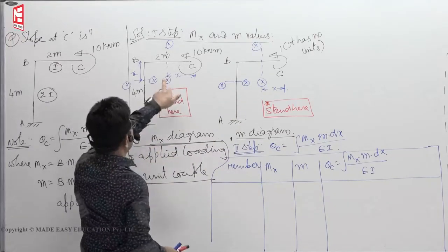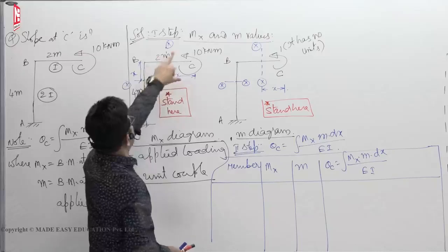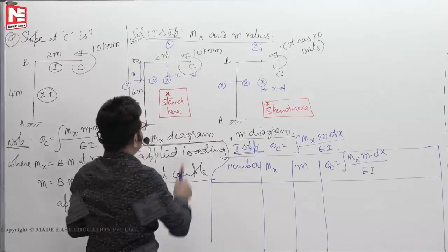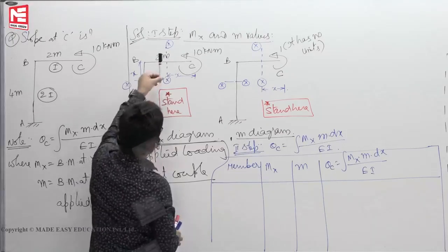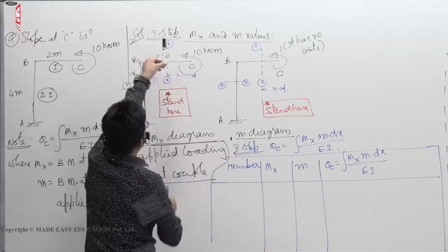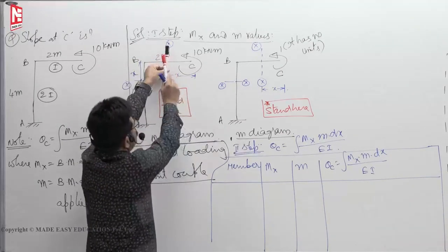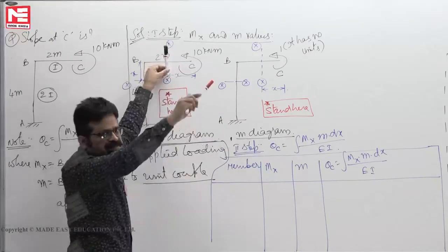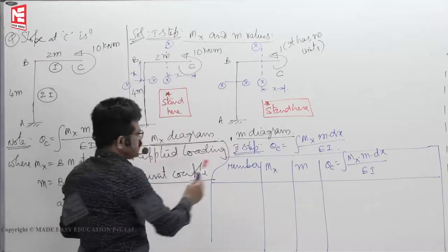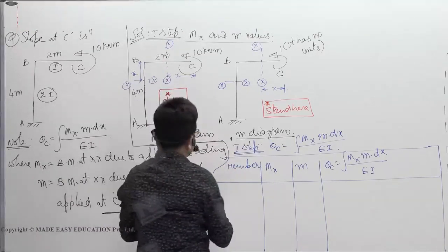Okay. Stand here means stand here, look right side. That way. Now stand here means this frame. You go to the frame, stand, go here and stand like this. Now section right side anti-clockwise. It will sag the member. So it is sagging positive, hogging negative, you can take it.